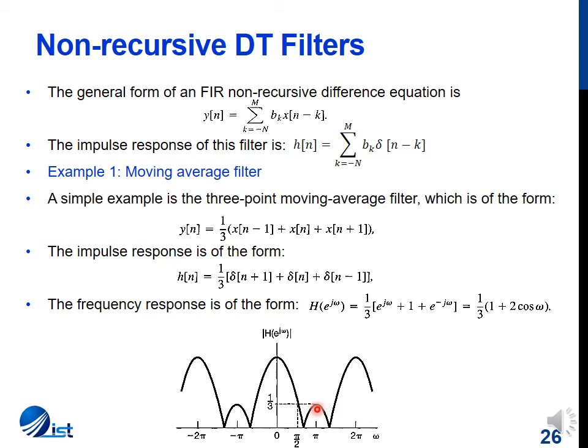Such a kind of filter is known as a low pass filter, and in practice the moving average filter is used as a smoothing or averaging filter to prevent high frequency transitions. Simply, high frequency transitions can be removed if we average out the value, because we also know that whenever we take an average, an outlying value averages out.